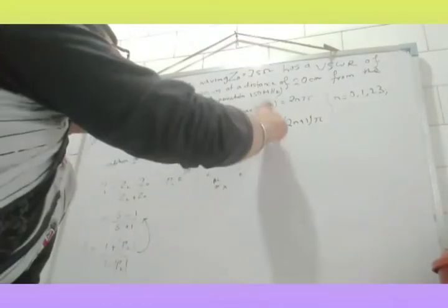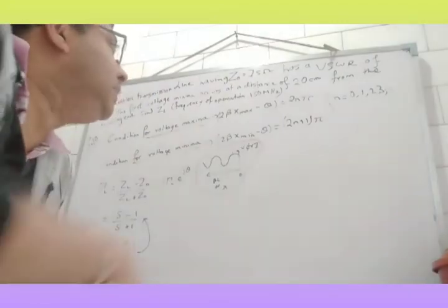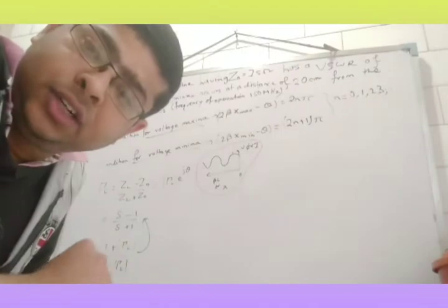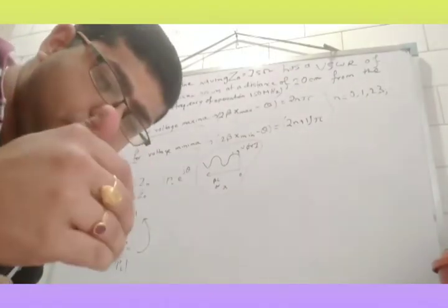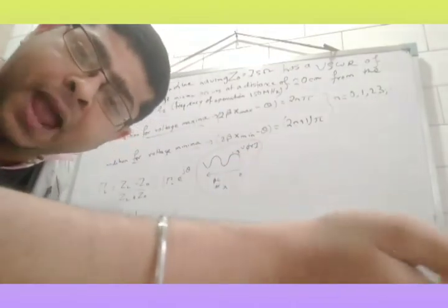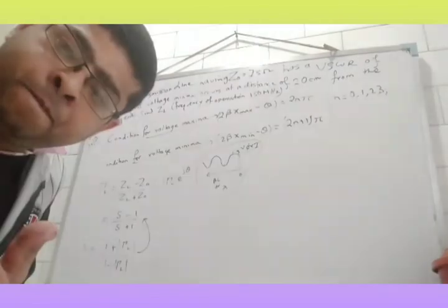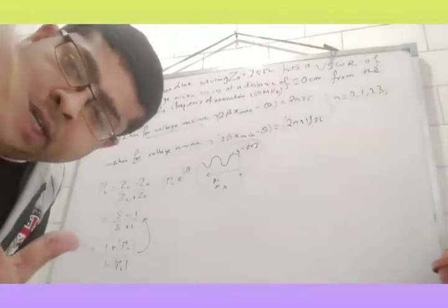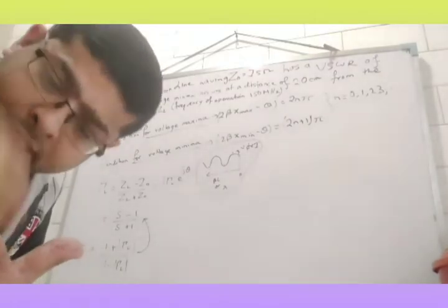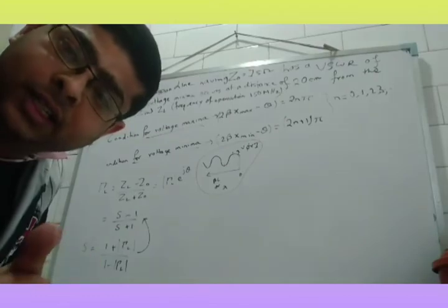And this theta, what is it? It is the angle associated with the reflection coefficient. The reflection coefficient basically tells how much of your wave is reflected back from the load end to the generator end. From generator to load, that means you are applying a signal, is what we generally call the forward direction.